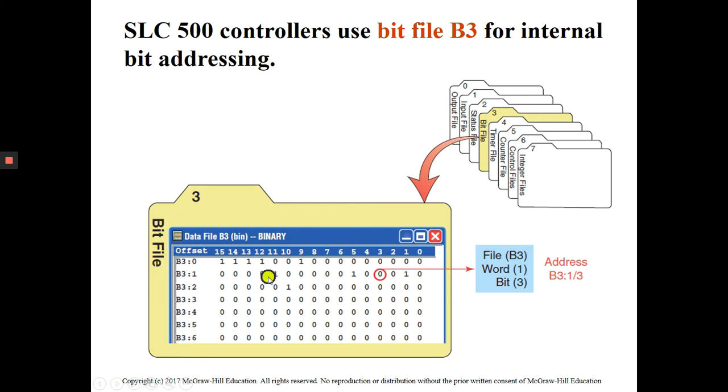Each internal relay consists of, for example, 16 bits or 2 words, and each bit here represents one terminal, or one bit can be used for the discrete case. When we want to represent a discrete input or discrete output, it gives you just either 0 or 1.